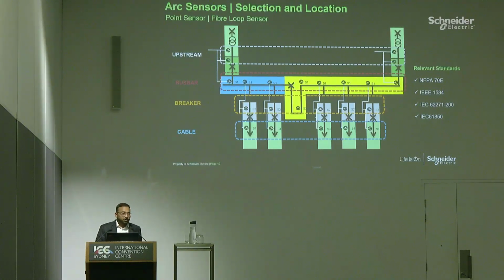Now, as a manufacturer, knowing the criticality of arc flash, and knowing that when I'm asking all of you to go for a dedicated arc flash system, I am ready to offer 2 milliseconds of arc flash operation time. So though the standard says go for less than 8 milliseconds or 10 milliseconds, Schneider offers less than 2 milliseconds of arc flash operation time.